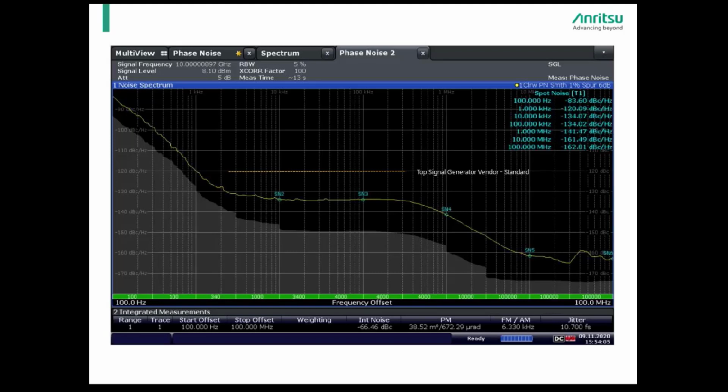Another key point to mention is that -125 dBc per hertz, typical specification, is the common and accepted value for the first tier of phase noise improvements through vendor phase noise options. For an accurate comparison, standard rubidium signal generators, meaning no phase noise options, have a typical phase noise of -132 dBc per hertz. Rubidium establishes new industry standards for phase noise, outperforming both standard and low phase noise performance of